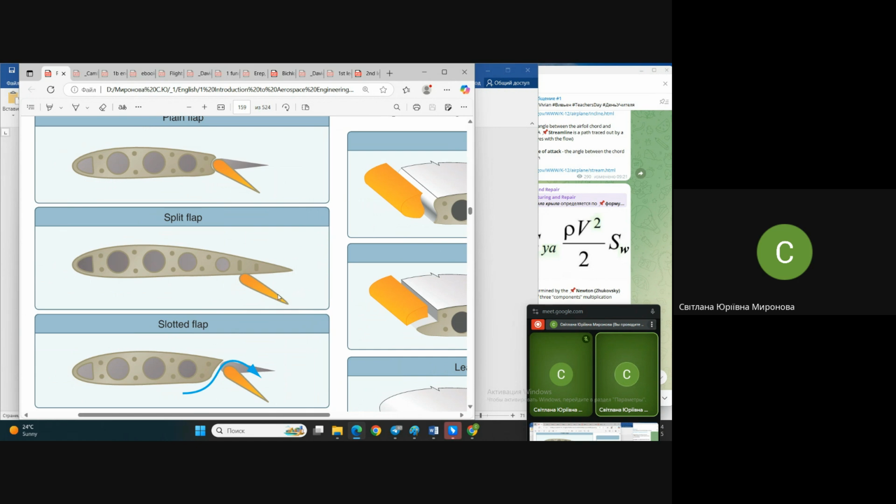Anyway, they exist. Slotted flap. What is different with respect to what? Look at this slotted flap and this plain flap. You see this arrow symbolizes that air comes, air may downwash this area additionally, air squeezes through this gap, a clearance has appeared.